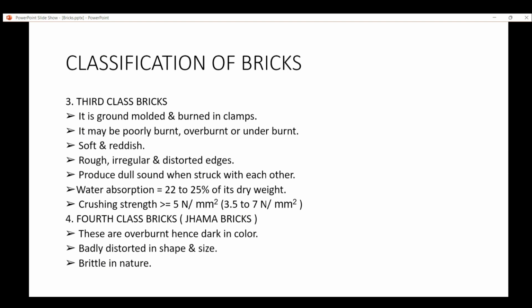The fourth class of brick. These are overburnt and hence dark in color, badly distorted in shape and size, and brittle in nature. We don't use this type of bricks. Rather, we prefer first and second class bricks for other uses of bricks.